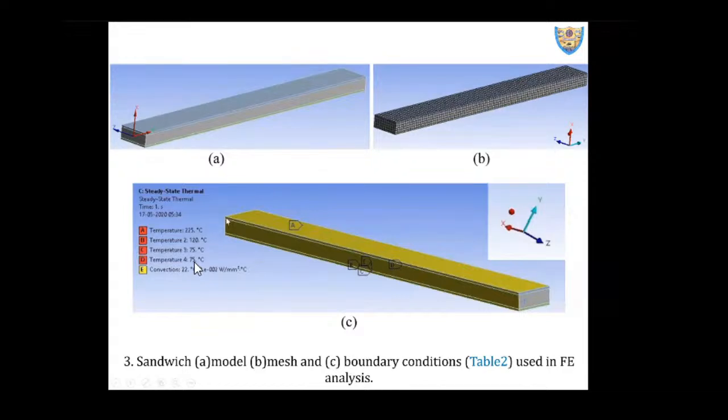So whenever you use a conventional manufacturing method, the sandwich is going to be the weakest at the interface. We have delamination, shear, everything happening. Let us say you have eliminated that by using an excellent adhesive, but still there is an adhesive. And this adhesive is not the parent material. What do you mean by parent material? Neither the skin nor the core material. And that's why wherever there are joints, let it be any conventional joints, joints meaning there is absence of parent material, and the material fails or buckles or has failure mechanisms governing from that point. The reason is parent material absence. So this is what we want to resolve, and thereby we exploited 3D printing in printing the sandwich all at once. Okay. And that's what we did.